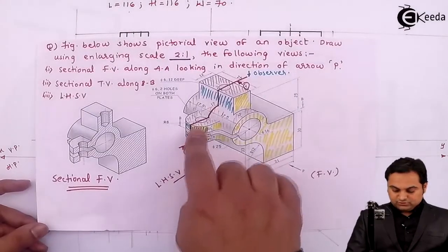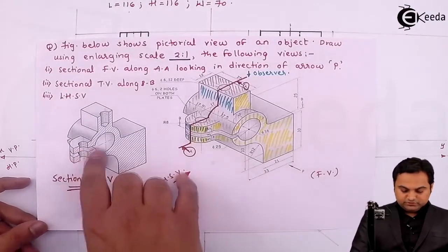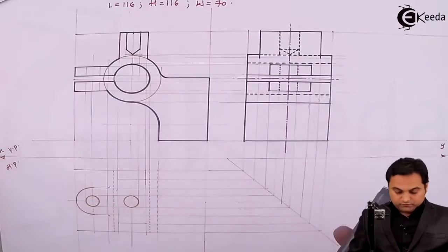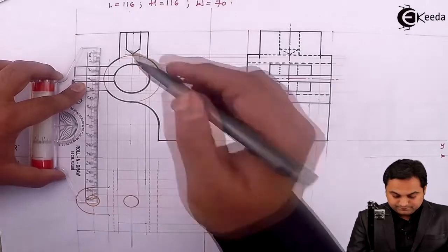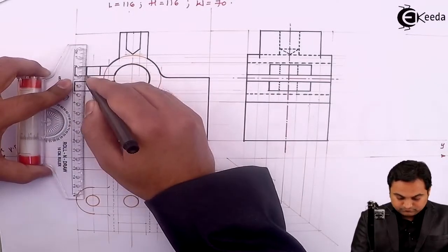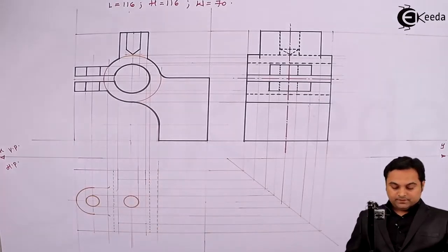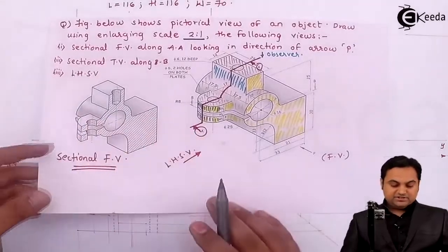Then as these two circles are being cut, it will look like this, that is, the surface will appear as a rectangle. So drawing vertical lines through them. So here is the portion inside which there should be sectioning.